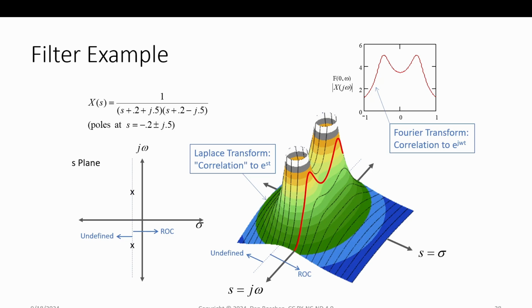And again, you see, hey, once we have this whole thing, which is given to us this way, we just see the poles, like 10 poles going up to infinity. And if we stuck with just saying, I want to sweep s to just stay on the j omega axis, we're getting the Fourier transform. So the magnitude of that surface when we stay on this axis, which is this red that I plotted here, and I'm showing it up there, that's the Fourier transform. That would be the frequency response of this low-pass filter.